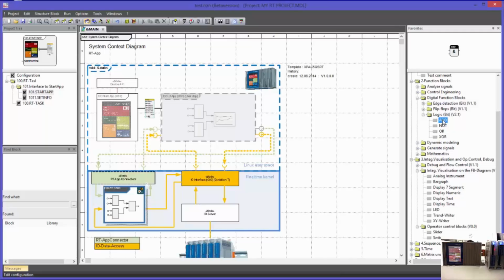The function block executes the actual functionality on the target system, the controller. The function block is the smallest executable element and was programmed in the system programming language C. It is available on the controller as executable code and it can be called any number of times.